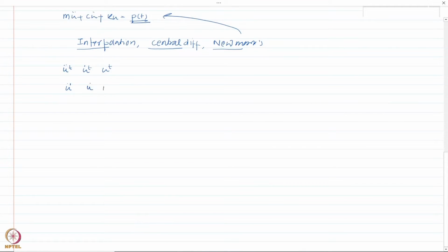Note here, relative velocity and relative displacement. Now, usually for a structural engineer, the total velocity is not of concern to us. What is of concern is basically the total acceleration, and I will talk about where we actually utilize that. But total displacement is also of concern to us.